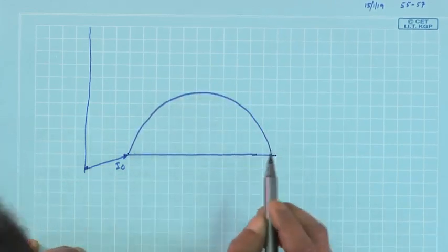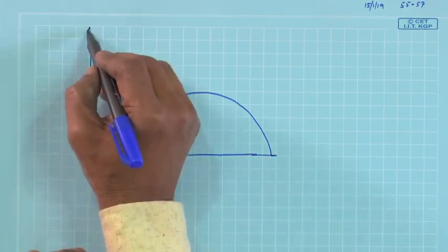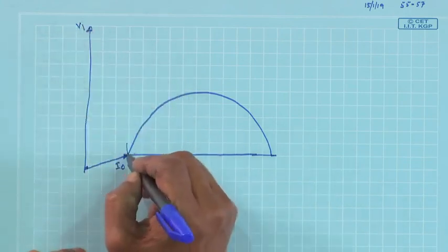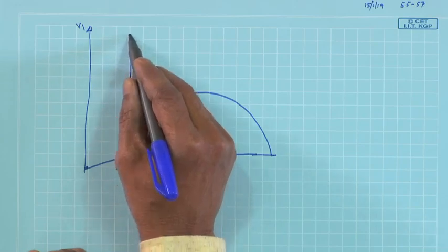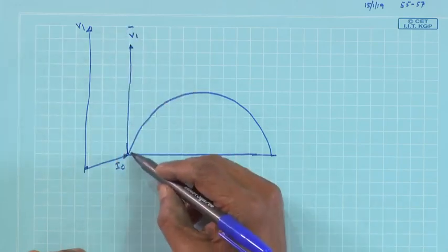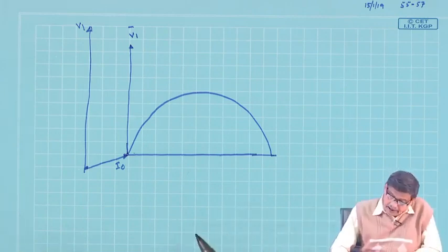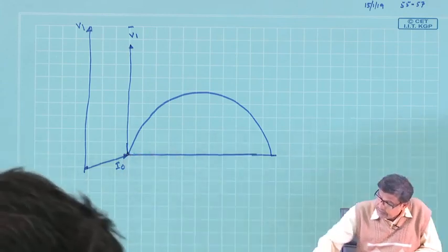Then as usual, this is your voltage V1. Similarly, here, if you draw a line parallel to this, that also is V1. So, this current is that I2 dashed, the reflected current, and at S equal to 1 it was like this.